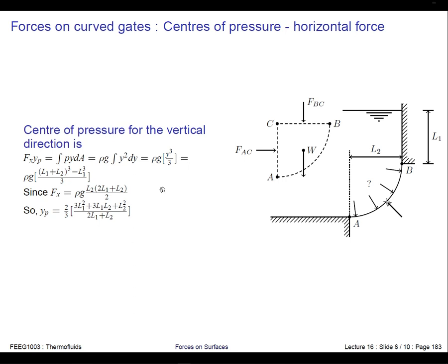effectively we take moments again, and we say that the force in the x direction, which we've already worked out, multiplied by some depth under here, gives me effectively my y coordinate in this little sub-volume. And we can do that by working out the moments along this surface.